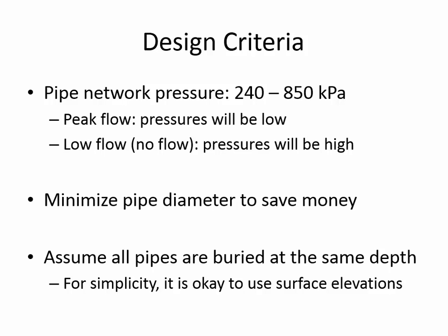But overnight, like in the middle of the night, if there just happens to be a period of time when no one is using any water, that's static conditions. And during static conditions, that means there's no head losses through the pipe. And so whatever pressure is being created within the network because of the tank being somewhere up on the hill is going to be in all of the pipes. And so you don't want to go above 850 kilopascal, or that's when valves can start to leak. And one of the locations that are particularly sensitive to high water pressures is people's water heaters.